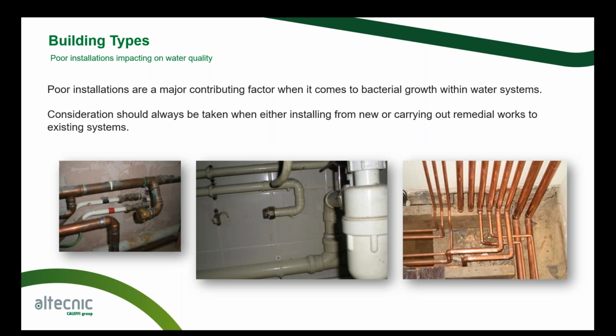I'm not going to say it wasn't lagged after the picture was taken, but obviously if you've got hot and cold water services running close to each other, we're going to start to get heat gain and heat loss across the pipework. So it's always important to keep the pipes well spaced apart, but also add the insulation, the lagging, to make sure we eradicate that risk of heat coming across.